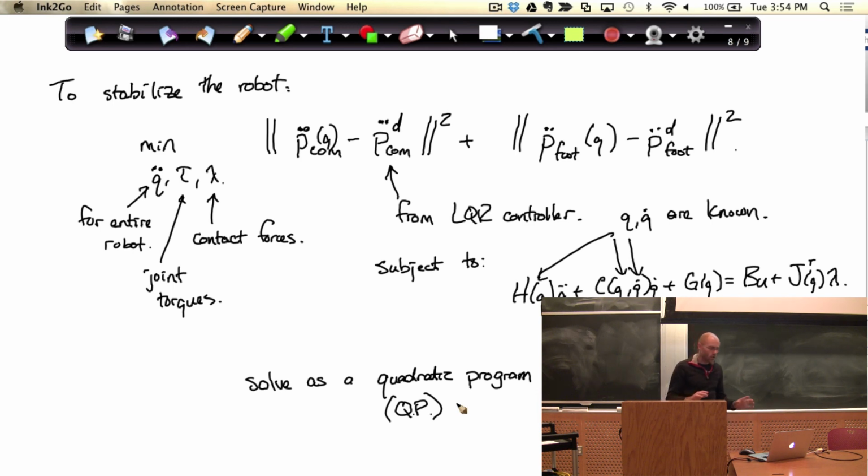Okay, so stepping back. In this special case of walking on flat terrain, my satellite with moving thrusters picture, all those thrusters can be summarized with a single point, which is my center of pressure. That's surprising, and it turns out to be surprisingly useful because of the connection between the center of pressure dynamics and my center of mass dynamics. I can prescribe the forces that I want to execute, and read out the position that my robot has to go through to do that. That's the big idea, right?